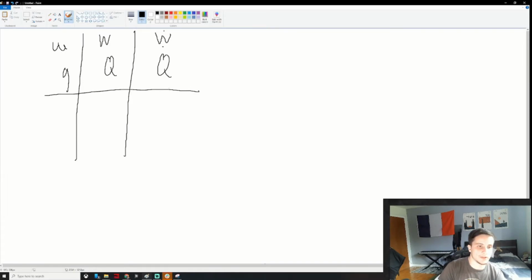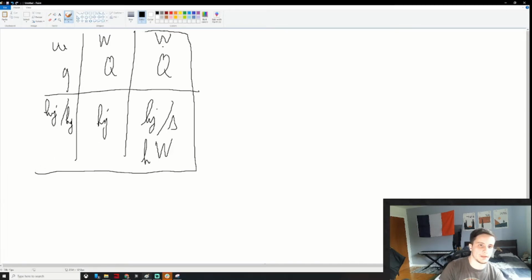What are their units? Small q, small w: kilojoule per kilogram. Big W, big Q: kilojoule. Big W, big Q with dots on top of them: kilojoules per second, or kilowatts. Okay, so that's the lettering that you should be using, that I'll try to use for the remaining tutorials. That's their units.